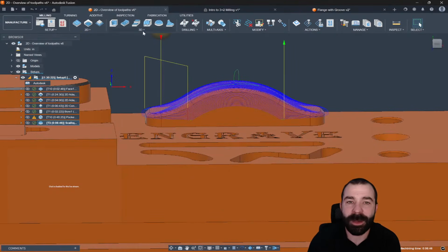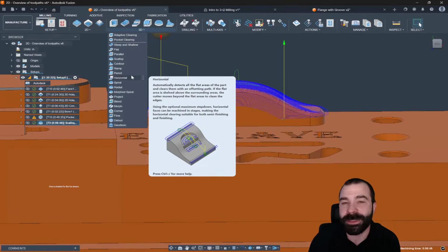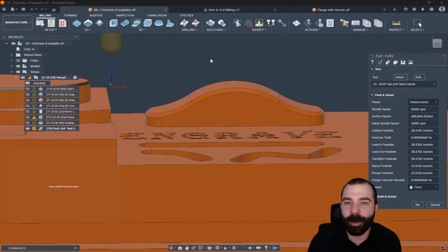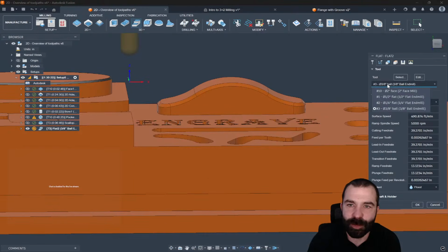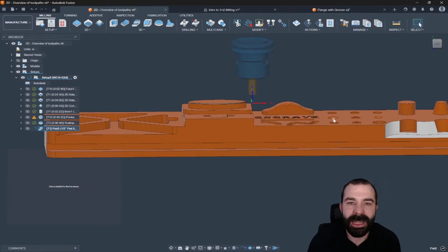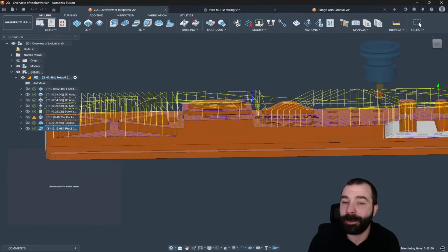So from there, we're going to go ahead and look at a few more other toolpaths. Now, this is where I would say we're going to actually pivot to drilling here in a moment, but I want to look at one more thing. So we will come back to something like the flat toolpath. Again, we're going to go ahead and do our 1/2 inch end mill. Notice here, once again, the settings are all basically the same. And because we are in 3D, it is model aware, and it's automatically finding anywhere and everywhere on our part.